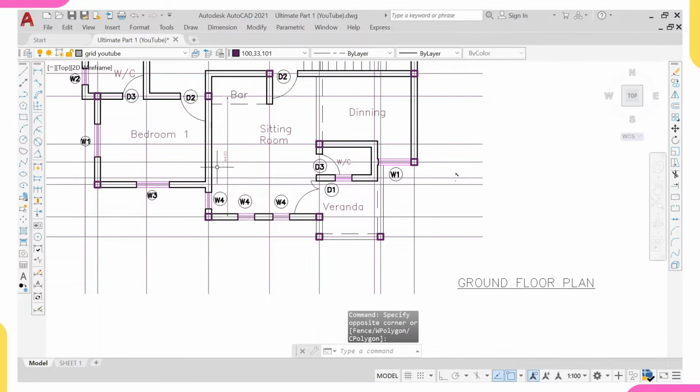So to save cost, because this is 4.4 meters, and I said that it should not be more than 6 meters, 4.4 meters is too small. So it will be able to carry the load coming from this side and the load coming from this side, and also this point load. So to save cost, I will remove this column.